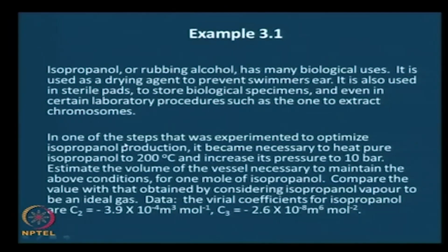And the first improvement that we saw was the virial equation of state, which we said could be written either in terms of a series in pressure or a series in specific volume. Then we had posed this problem to become comfortable with the use of virial equation and had given you some hints and an initial part of the solution. So, let me present the complete solution here.